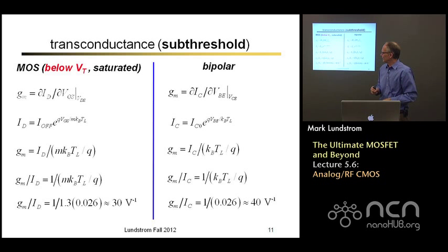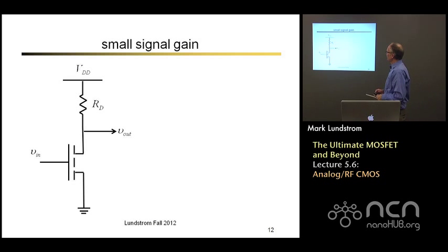The difficulty is the transconductance goes as the DC bias drain current. In the subthreshold regime, that's very small. So the figure of merit is good, but the actual transconductance is very small because the actual current is very small. But it's nice to understand that those two devices really are almost the same device in subthreshold.